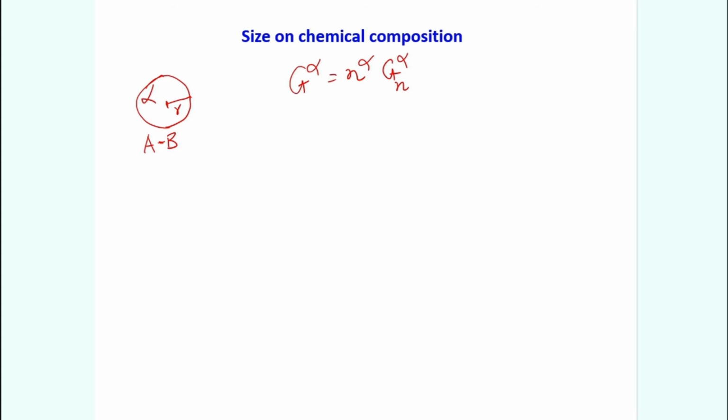Correct? Okay. Nonetheless, this is basically free energy of the bulk. We have not considered spherical particle or not. This is free energy of the bulk, big material, alpha. So, if you want to know the total because of bulk and the surface, then you have to add gamma into surface area of alpha. That is obvious, right? This is the free energy of alpha in the bulk, this is the free energy of the surface because of small size actually. For bulk, meaning very big, the surface area is very small, you can ignore the second term. But in a nano particle you cannot, you have to consider this term very seriously.